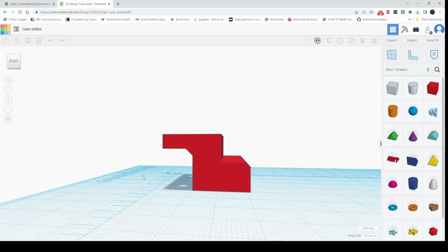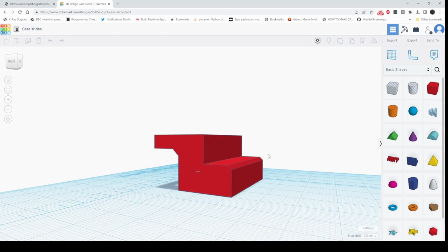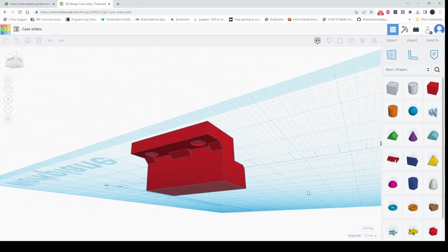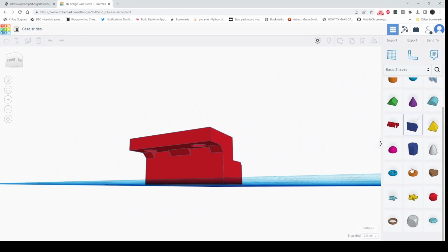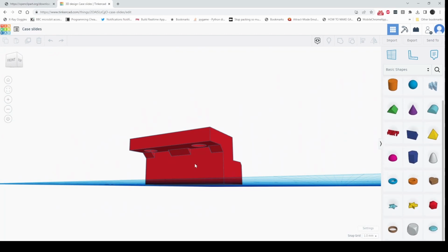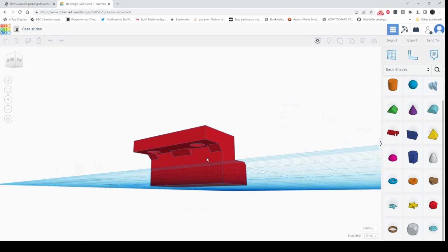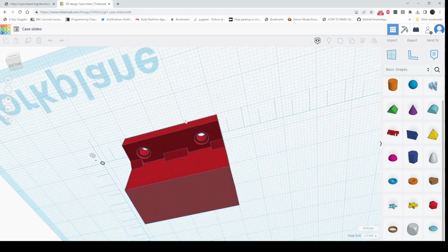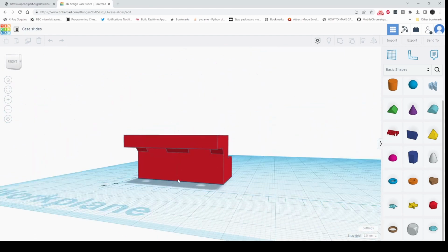So I measured the lip that surrounds the hinge and the top of the box. And I applied it into this L shape here, with a little bevel just cut out so I could slide it in nice and gentle. I then added some wedges. Not the dude from Star Wars, Ewan McGregor's uncle. Just some wedge shapes there and merged them in. I also added some countersunk screw holes to it, which are M4 size if memory serves.